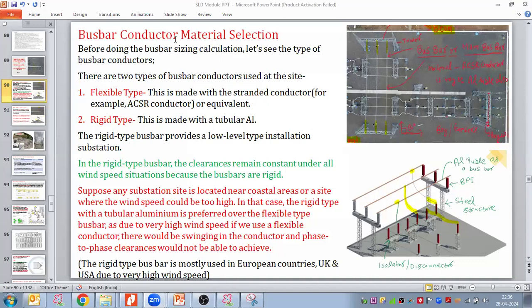In 400 kV level, we can use the VT, sir. Yeah, why not? We can use the VT. We use the VT for the tariff metering purpose, but the cost of the VT would be high.